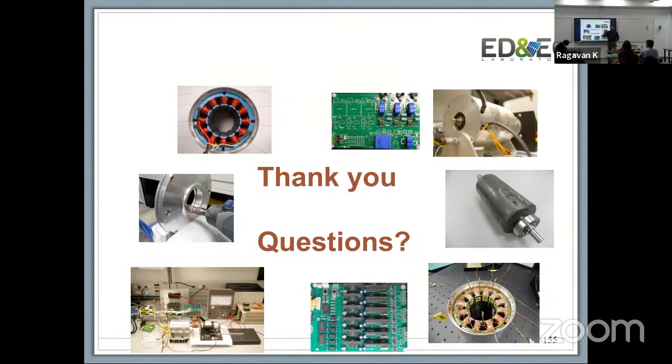So for sensorless methods, you have to define a threshold. We have done some work on switched reluctance machines, which we'll talk about tomorrow, specifically where we identified what happens if you apply a certain amount of current. So you have to have a sensitivity analysis in the motor to tell you how much current you can apply before you end up creating negative torque. Sometimes negative torque is a consequence you might be okay with, but a lot of times you're not. So sensitivity analysis is very critical for that.